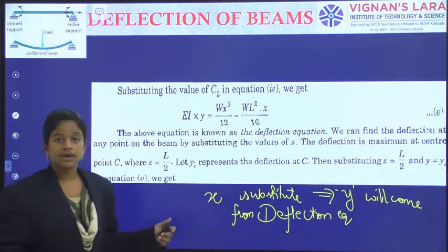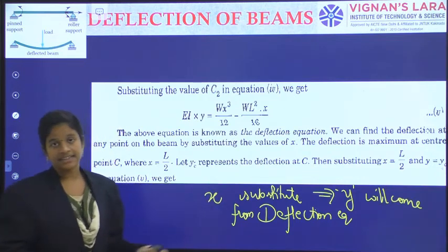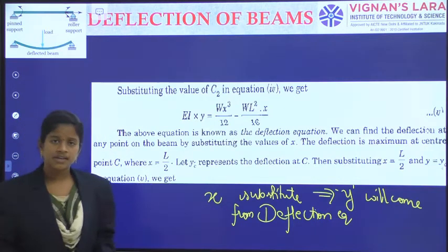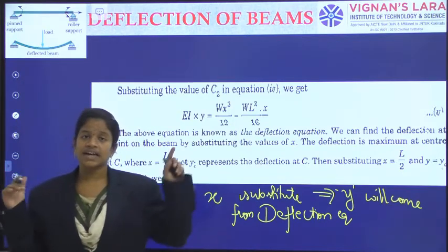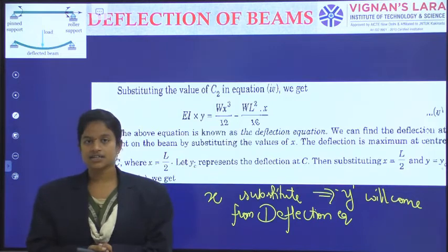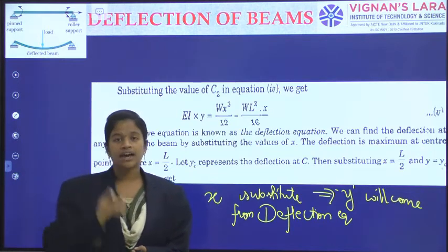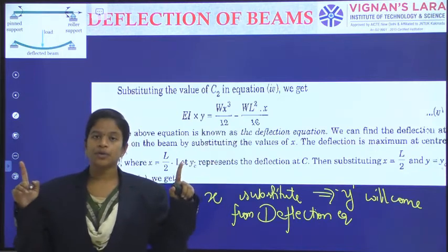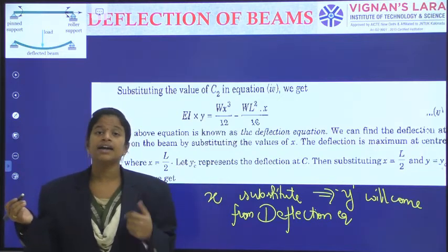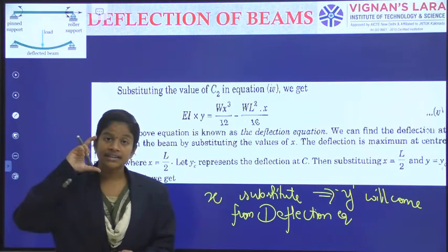Right? So this is my equation and we can get these values. I have used a boundary condition and evaluated. Like the previous, at point A and at point B I have calculated the slopes, and at the center point the slope is 0. Now I am considering that at points A and B the deflections are 0, and I am calculating the deflection at the C point.